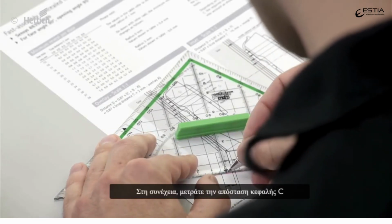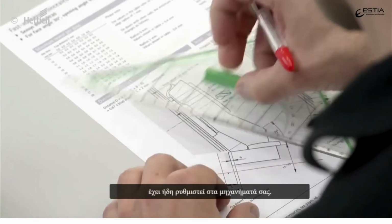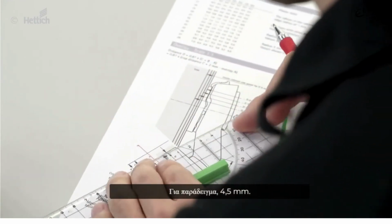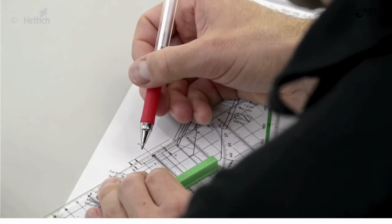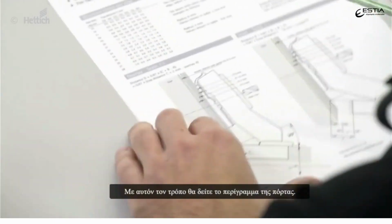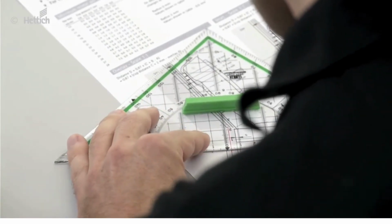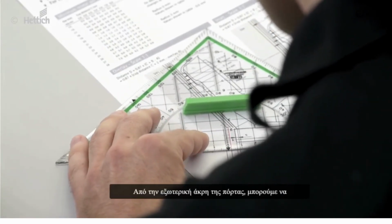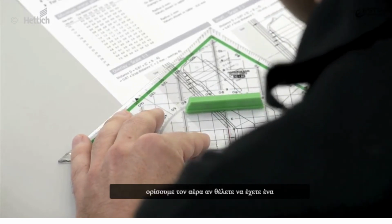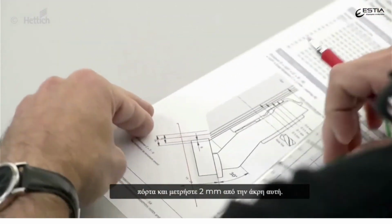Next, you measure the cup distance C and mark it into the drawing. You may choose a measurement that is already set in your machines, for example 4.5 mm. This way you will see the outline of the door. From the outer edge of the door, we can set the reveal. If you like to have a 2 mm reveal, prolong the line of the outside door and measure 2 mm from this edge.